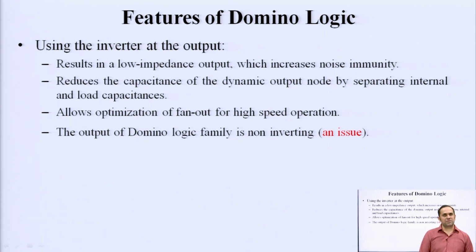Reduces the capacitance of the dynamic output node by separating internal and load capacitances. Okay. It allows optimization of fan out for high speed operation. Okay. And the output of a domino logic family is non-inverting, right.